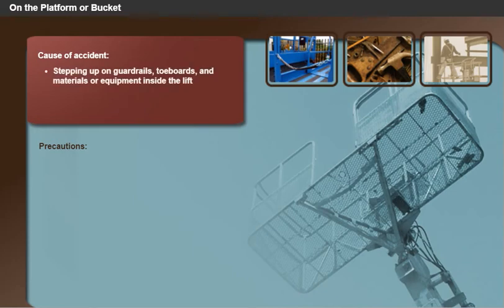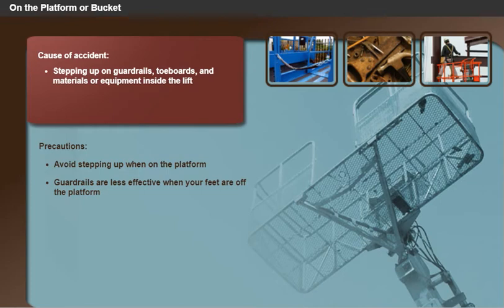Stepping up on guardrails, toe boards, and materials or equipment inside the lift. Avoid stepping up when on the platform. When you're above guardrails, they will not provide you with the same level of protection as when your feet are on the platform.